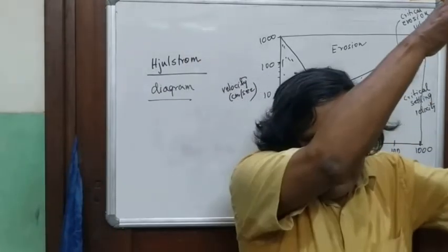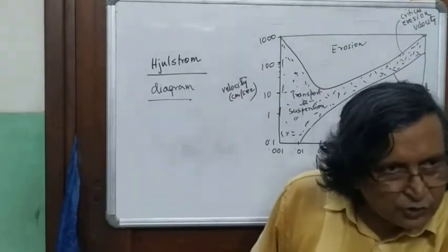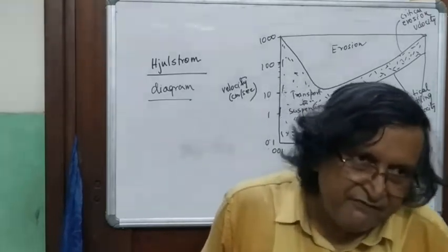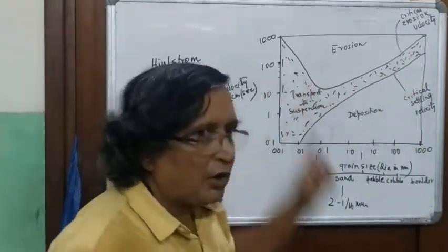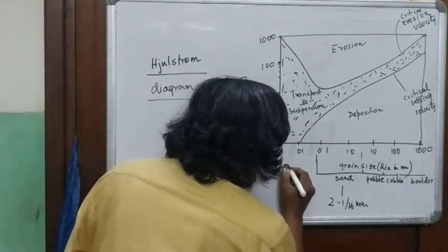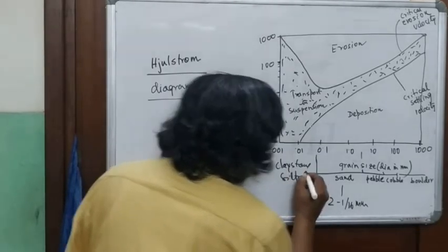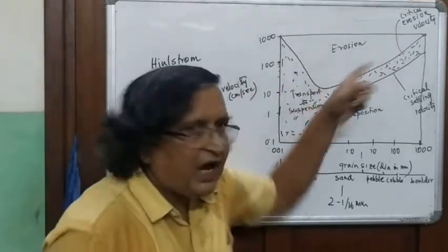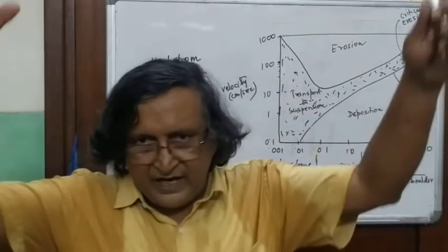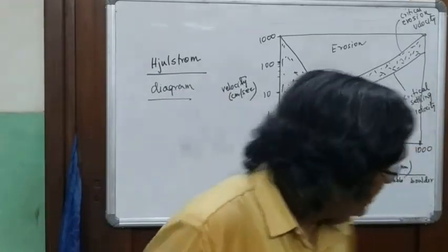If you imagine a river system flowing down, you can move sand in suspension with the smallest speeds, but it will be very difficult to move the boulders or the finer-grained material, the claystones and siltstones. Once you have deposited clay or boulders, you require high speeds, but sand would require low speeds to be eroded and taken in suspension.